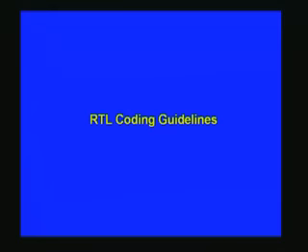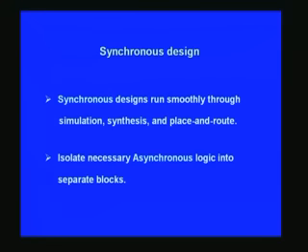It is basically a synchronous circuit design, which you are already used to, and it signifies the data flow and how you process the data. Basically it is a synchronous design which should naturally run smoothly through simulation, then synthesis, and finally on place and route. In order to do this, you have to isolate the combinational and sequential circuit.